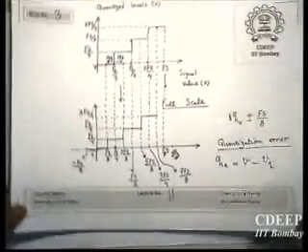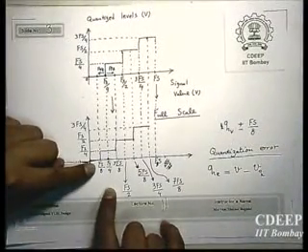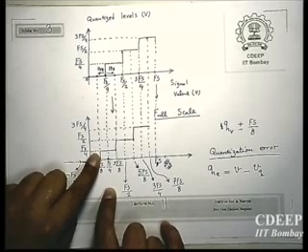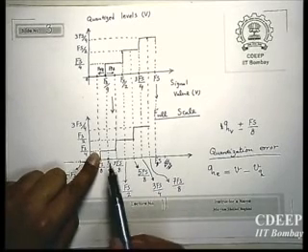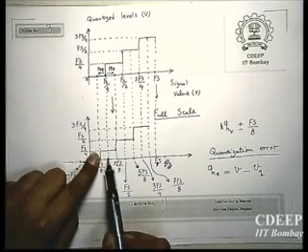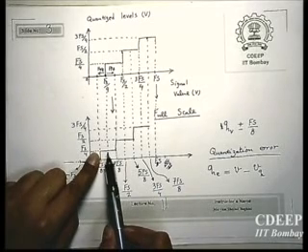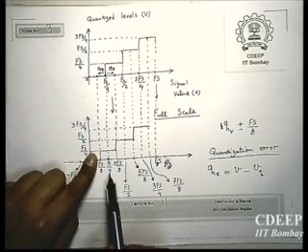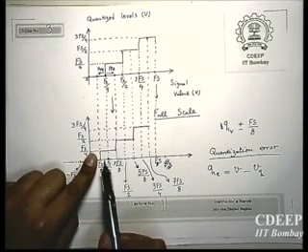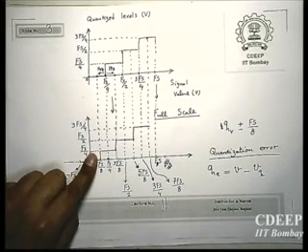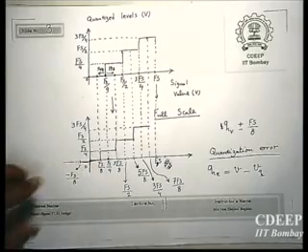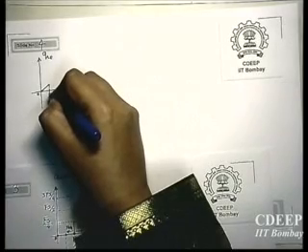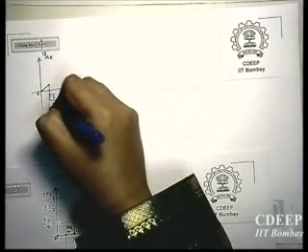Now you reach Fs by 8, then your value jumps to Fs by 4. However, if your input value is Fs by 4, your output value is correct. But for values between Fs by 8 and Fs by 4, your signal is less than your quantized level. Therefore, you have negative error, right? Therefore, you have a jump over here. I just show it in this way.